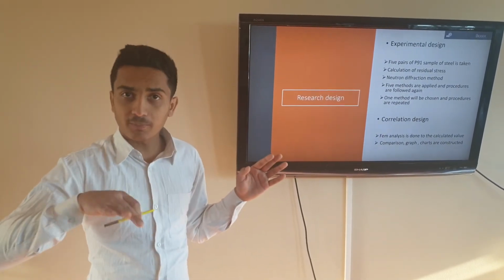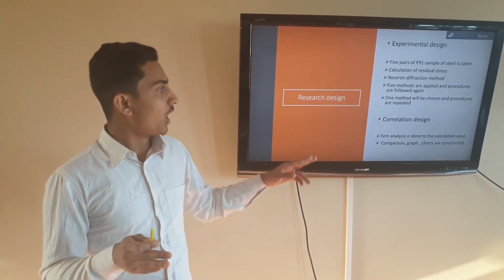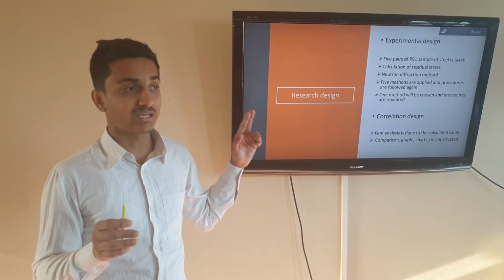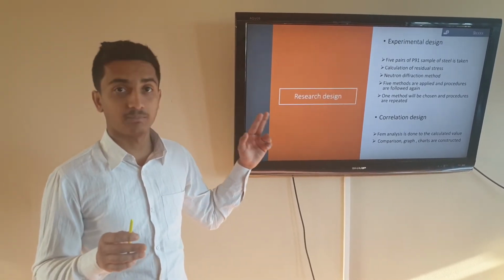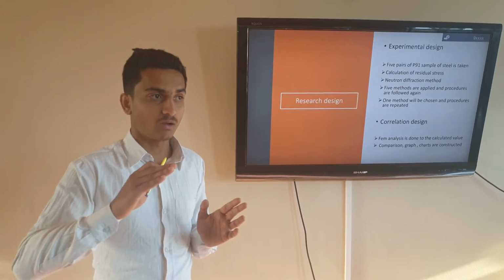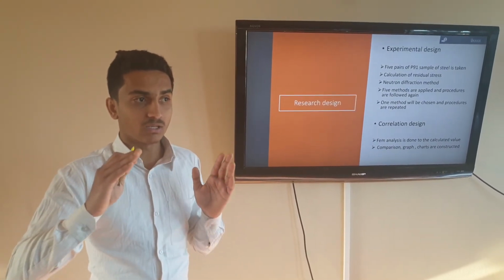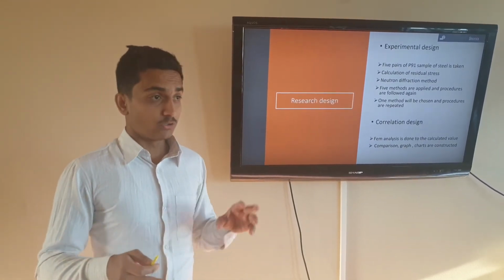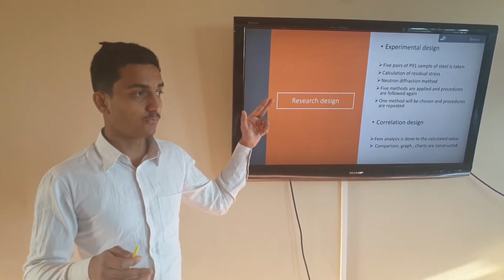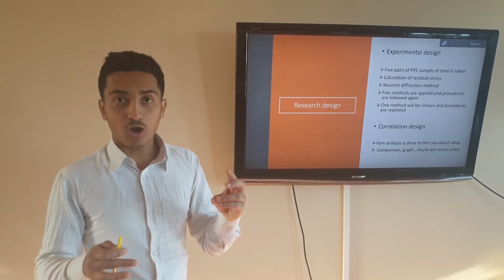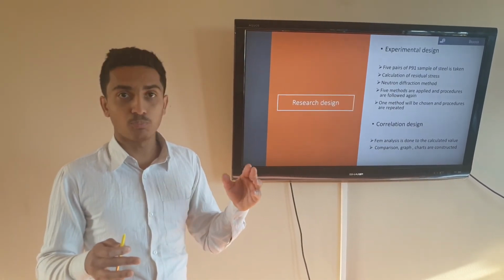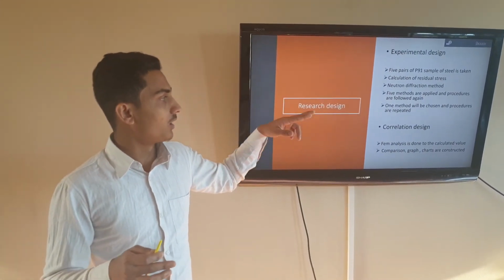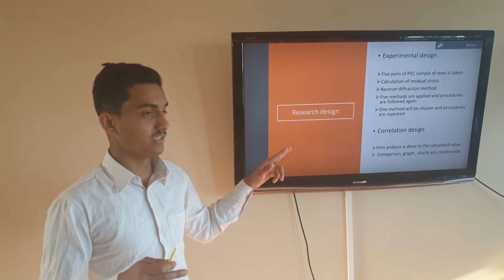Here, out of many different methods to calculate residual stress, the neutron diffraction method is followed as it is one of the latest and most reliable diffraction methods, which shows very accurate results of residual stress. Then, the 5 methods that were discussed before, cooling, ultrasonic impact, vibration, post-weld heat treatment, are used to reduce the residual stress.